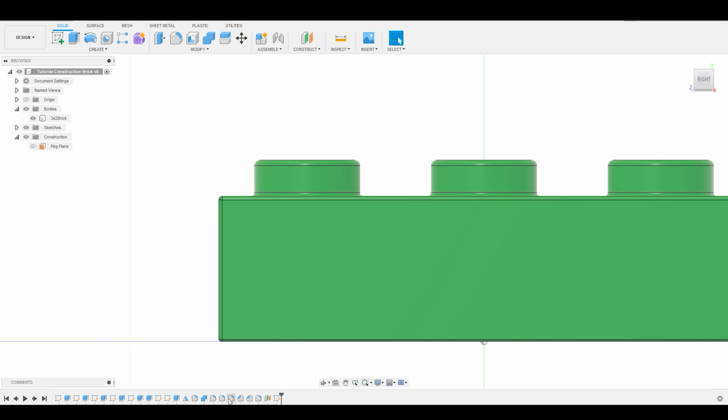I know where all of these fillets are. They don't reference anything else, so I can scrub them forward in my timeline. Excuse me, I'm actually going to pull my offset plane back before I did my fillets. I'm going to scrub these back in the timeline to before I did the fillets, to suppress those fillets so that I can now pull some of this more native geometry. All right, and I'm going to edit this sketch.